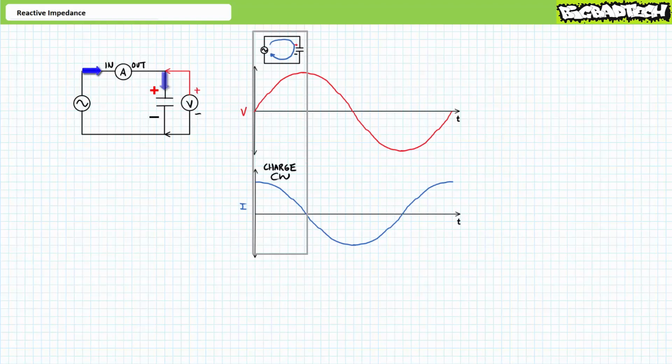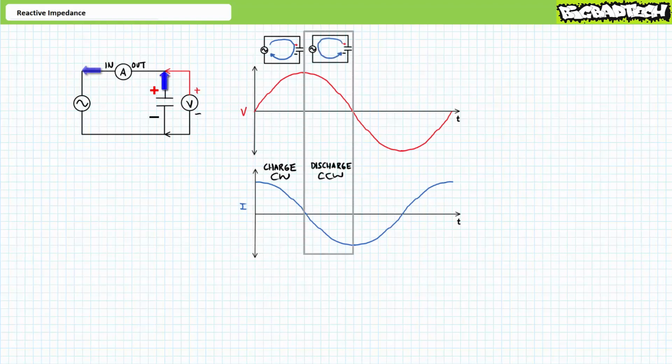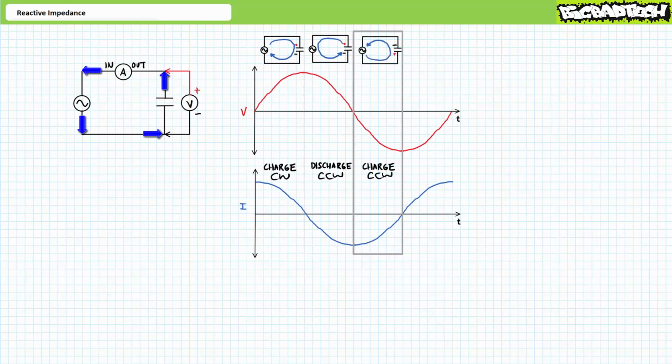The first half of the cycle is easy to explain. The initially uncharged capacitor at first experiences a large surge of positive or incoming current. As capacitor voltage rises, current decreases in magnitude and then stops altogether when the capacitor reaches full charge. The fully charged capacitor then starts to discharge. As capacitor voltage drops, the capacitor experiences negative or outgoing current. Here's an important switchover. Once a capacitor fully discharges in one direction, it seamlessly transitions to another charge cycle, only this time in the opposite direction.